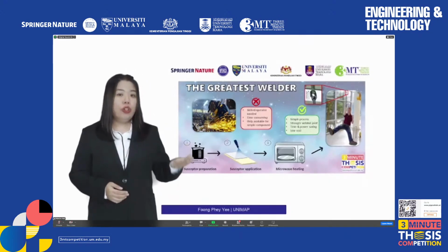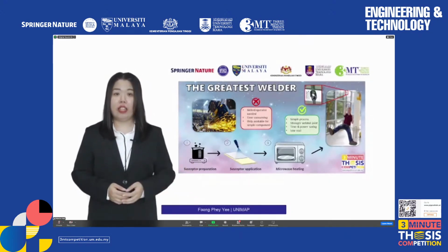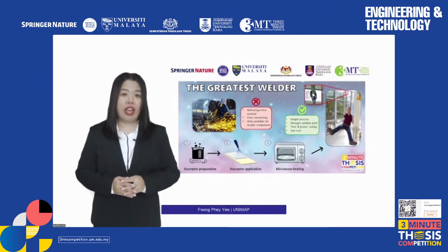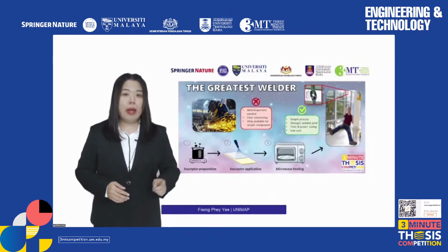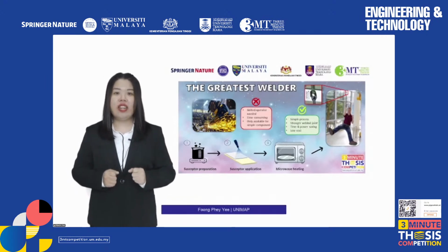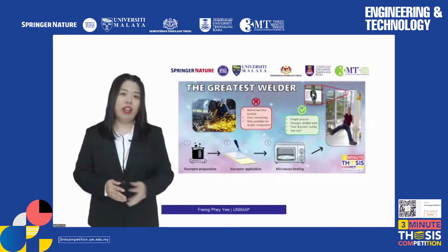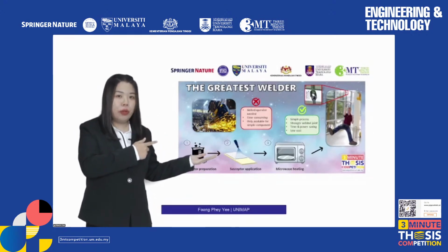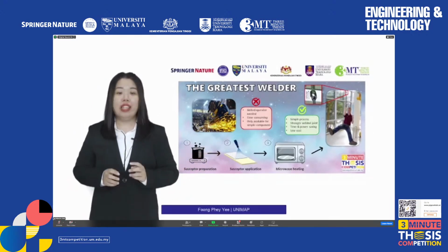First, the susceptor not only functions to melt the plastic, but also acts as a nanofiller in the formation of the nanocomposite welded joint. From the experimental results, the microwave welded joint is 275% stronger than the neat plastic product itself, as a man can hang in the air by relying on these small microwave welded hooks. It's cool, right?